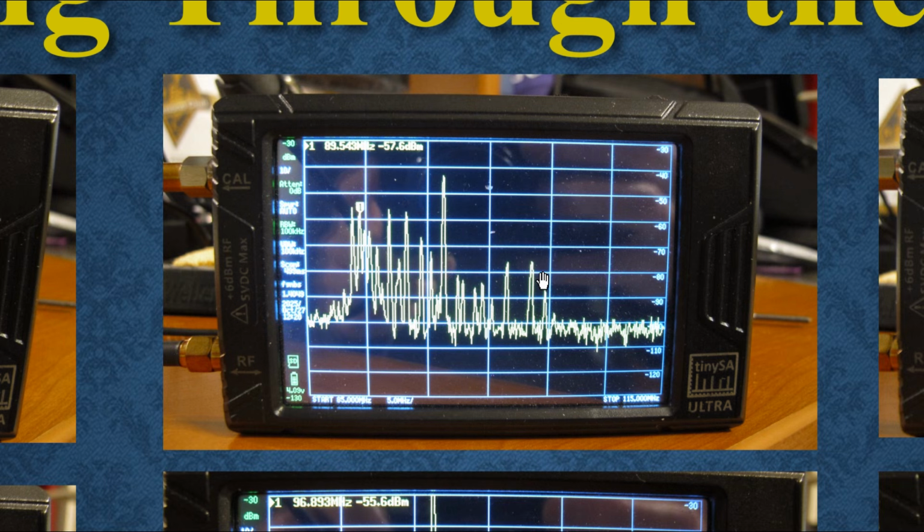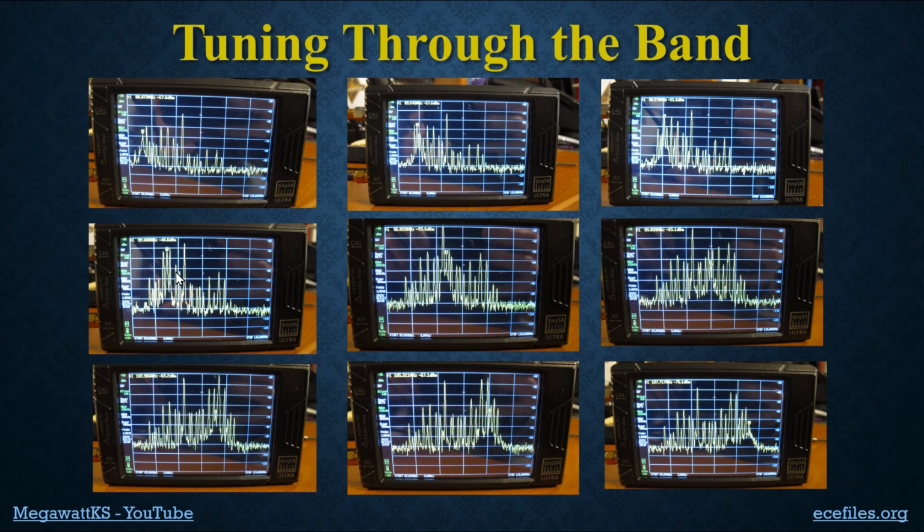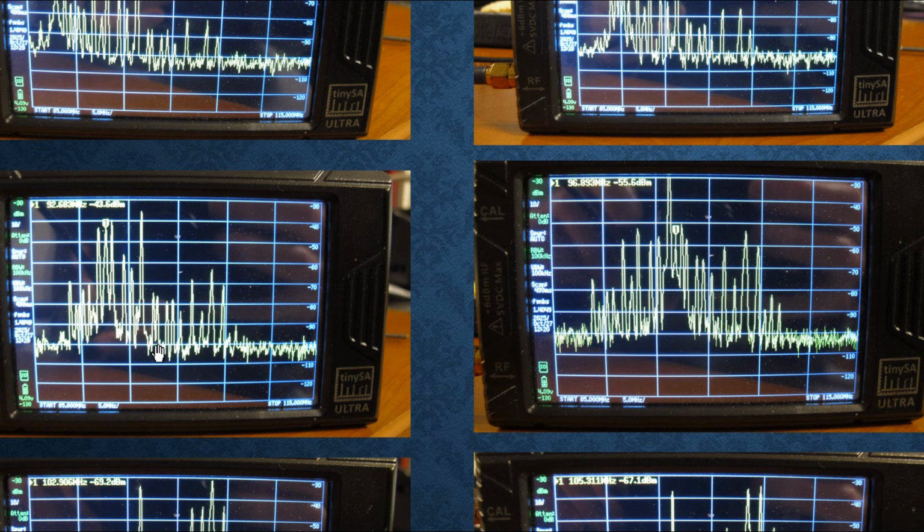And I'm just going to sample a couple more of these. Here's a whole bunch of them. One problem is that if we tune close to the strong guy, then the filter doesn't roll off fast enough, but it is doing a pretty good job. So let's compare these two. There is a signal here that we can't even see that has now been brought up to a level that's acceptable. The strong guy is over the top, but the top is only minus 30 dBm, so we might still be okay on that. So even though we're only a few hundred kilohertz or megahertz off of this center, we're able to pull this weak signal that's in the noise floor out.